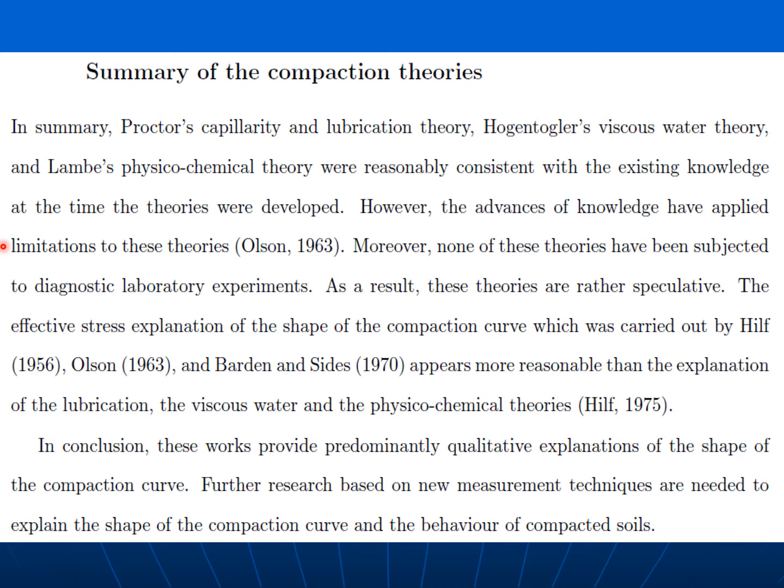Moreover, none of these theories have been subjected to diagnostic laboratory experiments. As a result, these theories are rather speculative. The effective stress explanation of the shape of the compaction curve, which was carried out by Hilf, Olson and Langfelder, and Sides, appears more reasonable than the explanation of the lubrication, the viscous water, and the physicochemical theories.